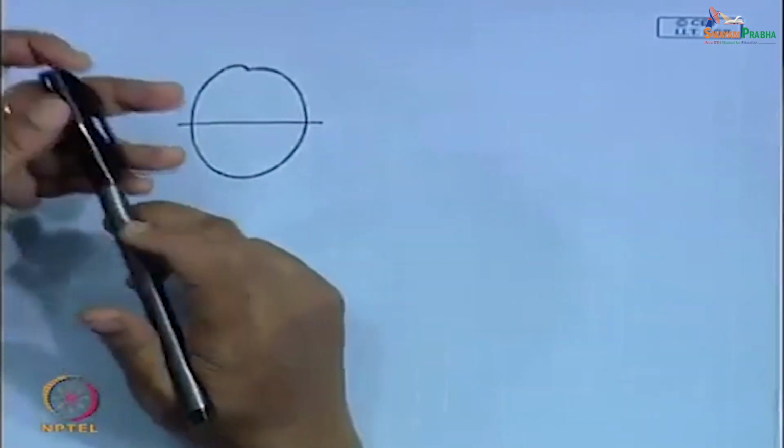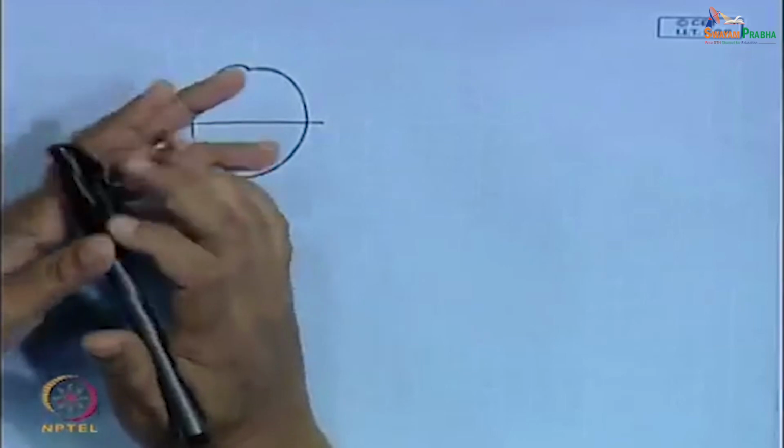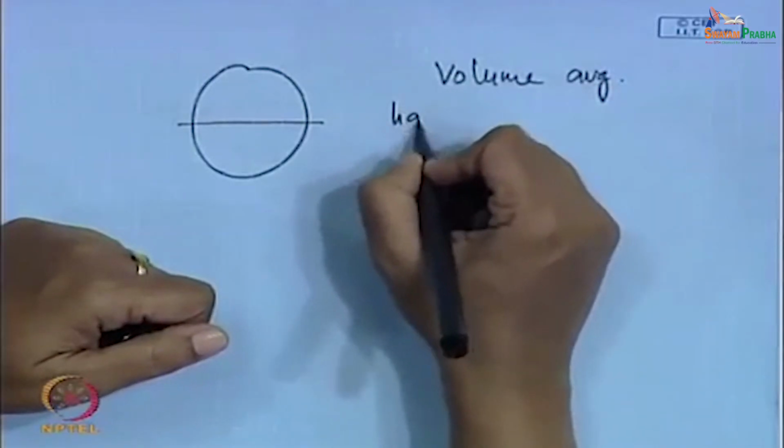So, before I proceed, I would like to spend some time on the different definitions of holdup, their mathematical expressions and how to convert them into volume average void fraction, because that finally gives us the in situ composition. As I have already told you, the basic definition is definitely the volume average liquid holdup.